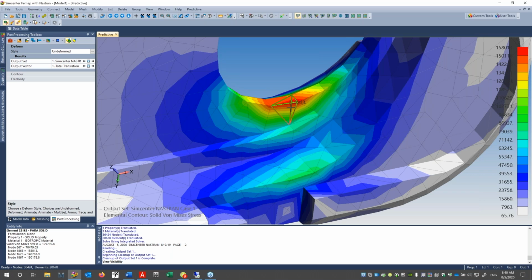If I'm really picking around for stresses, I like comparing the centroid, which are stresses interpolated from the integration points to the center, versus stresses that are extrapolated out to the corner points using the isoparametric function, the shape function for the element. And I like to say, okay, the amount of work being done by the shape function is the difference between the centroid out to the nodal points.